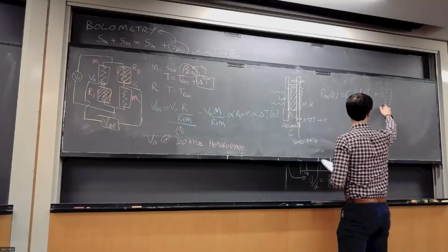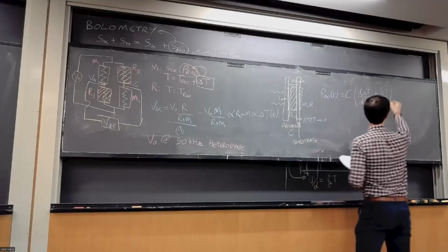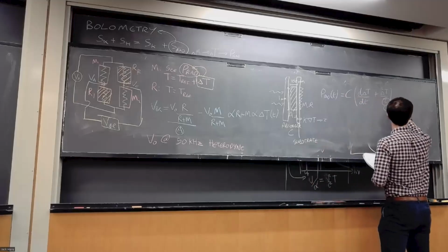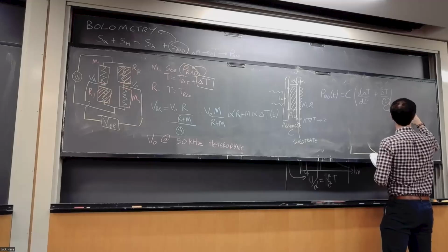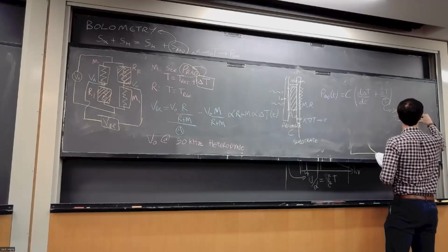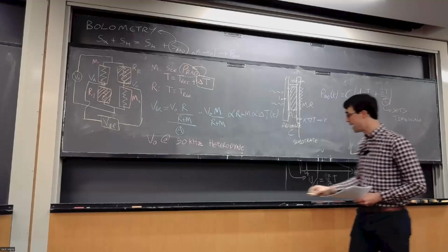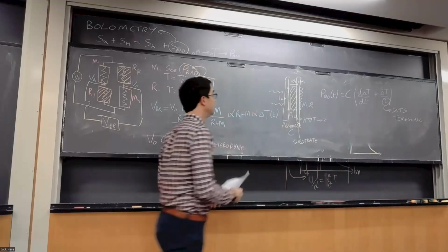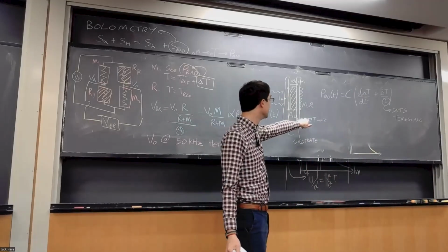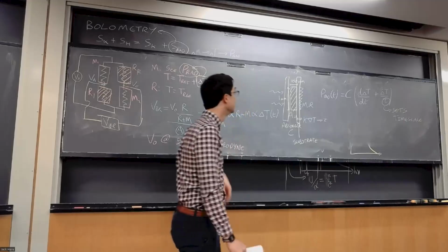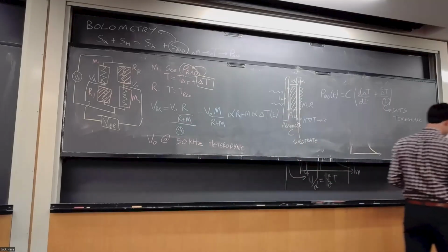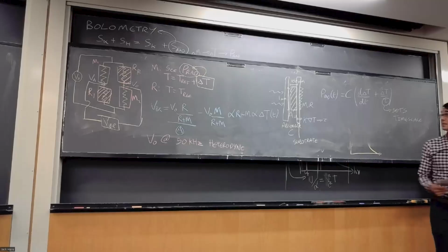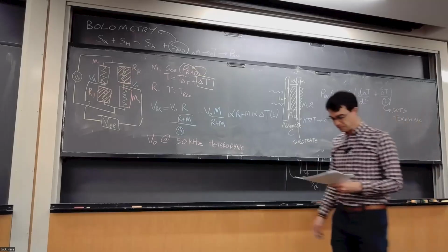And effectively, this tau here sets the time scale at which we can measure. So the larger tau is, the slower our measurement of the radiated power is going to be. And if tau gets very large, because we've got a very thick substrate here, or it doesn't have very good heat transport, then we're going to have a very poor time resolution of our radiated power. And of course, we'd like to have a nice time resolution of that.